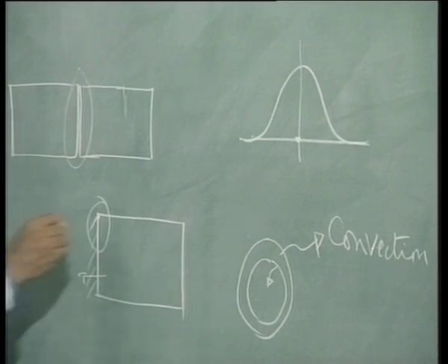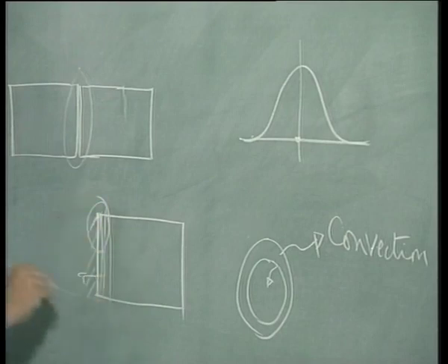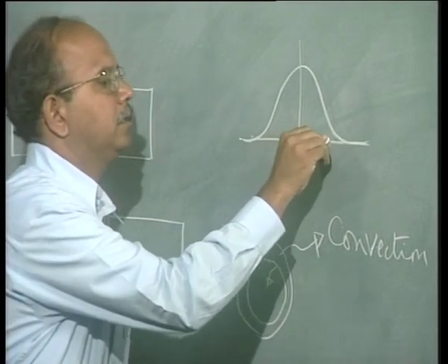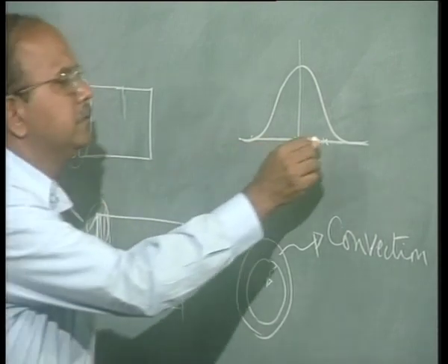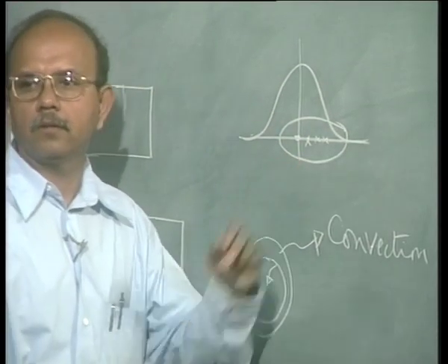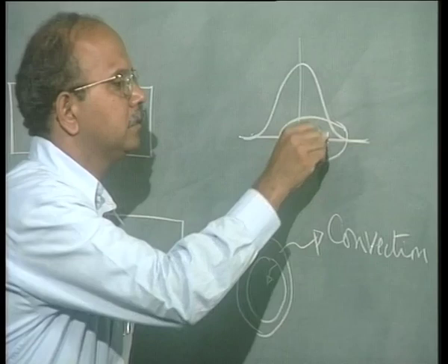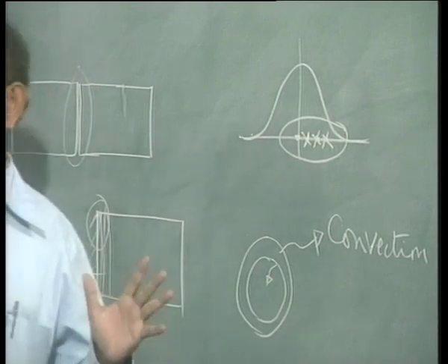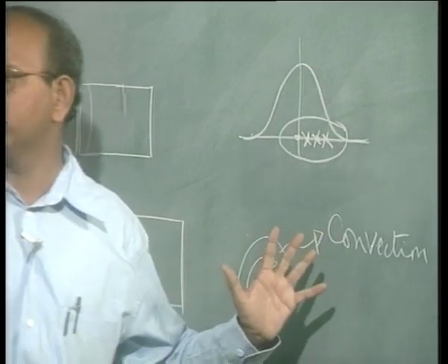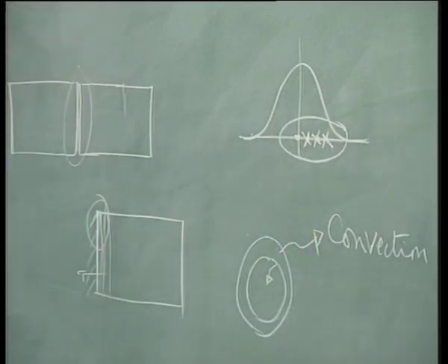If I just magnify this place, then you can see that that is the center line, that point the same as this point, then you can see that the flux has a Gaussian distribution. Okay. So, in other words, I have a number of nodes here, all the nodes sitting in this place are going to have the heat input. Look at these points, okay. They are the nodes that are sitting very near the place. So, as far as the thermal problem's boundary condition is concerned, it is not a big problem, but there is an issue when I put down the boundary condition for the mechanics problem.